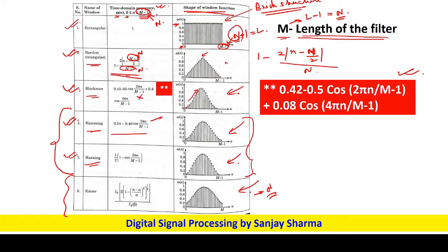Like the Blackman window, the Bartlett window also has a sudden increase, rises to a top, and from there drops down again. This increasing and decreasing, the roll off or the slope, is quite high. Because of this, since the roll off of the Bartlett and the Blackman windows is quite steep, the Hamming window and Hanning window are mostly preferred. It is not that the others are not used at all; they are also used under some special conditions, but for our case we will be mainly focusing on the Hamming and the Hanning windows.